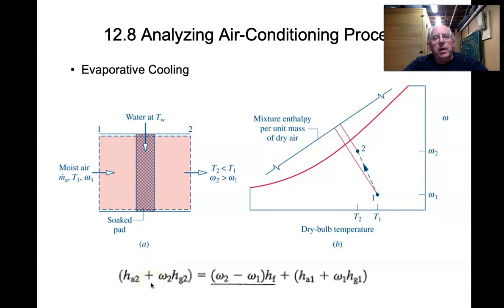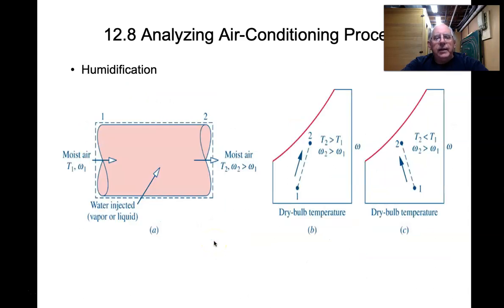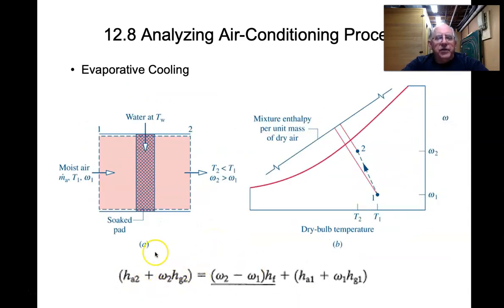What is missing in this first law equation is just the m dot a. And that m dot a, which we saw before when we wrote this equation, was in each of the terms. And so all that was done is that this bracketed term here has been set equal to each other. And the combination of these two terms is actually pulled off of the psychrometric chart.